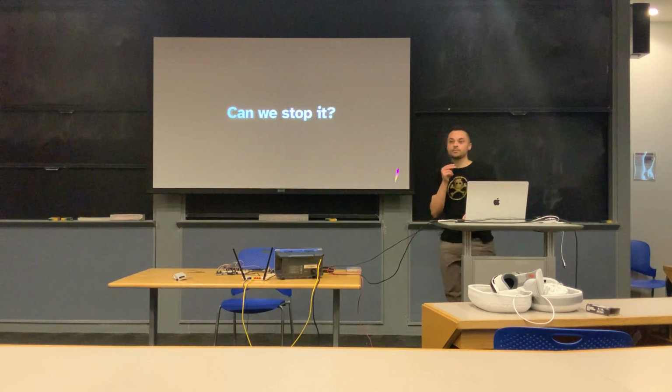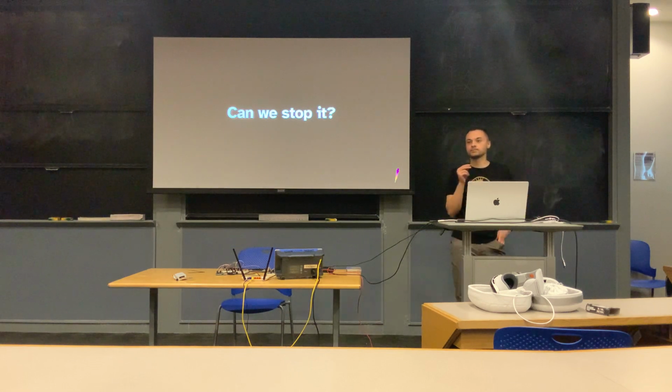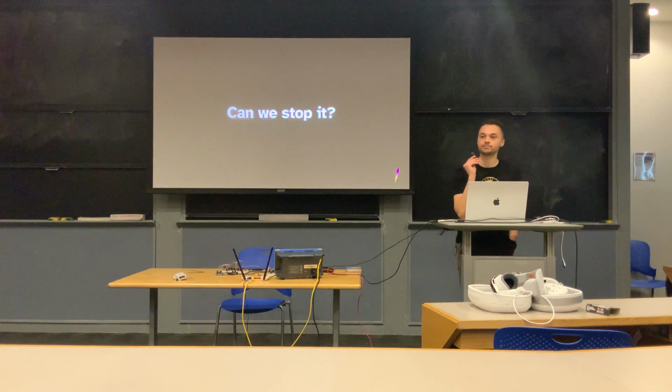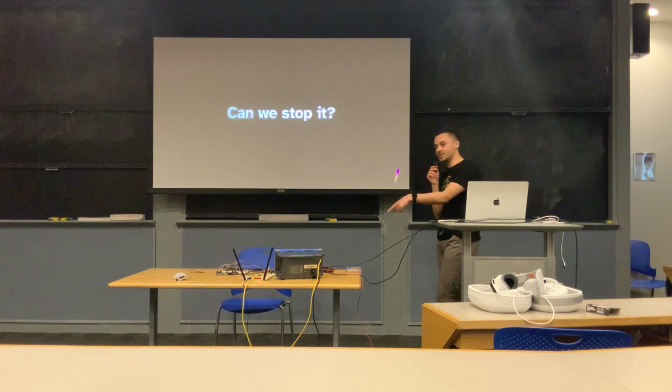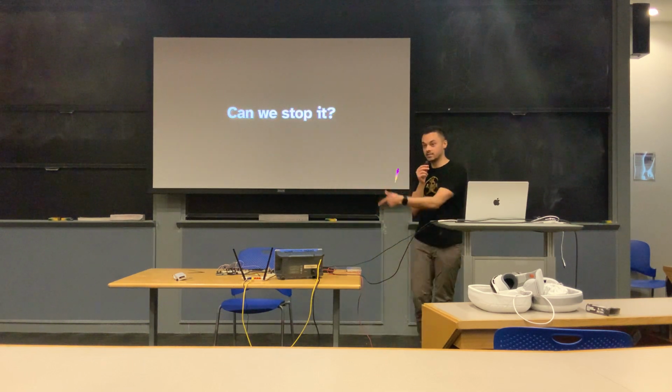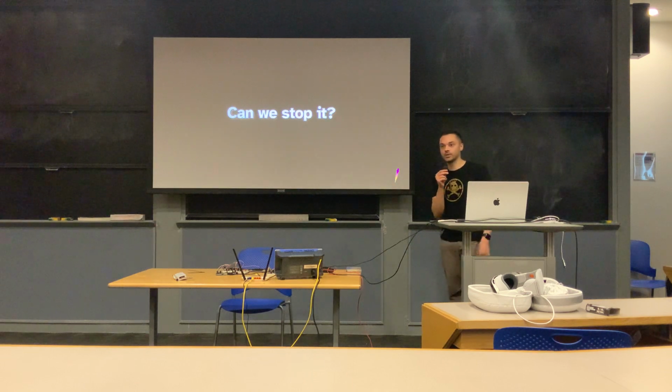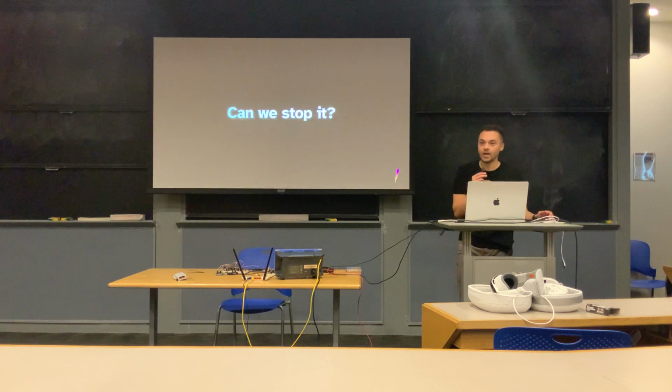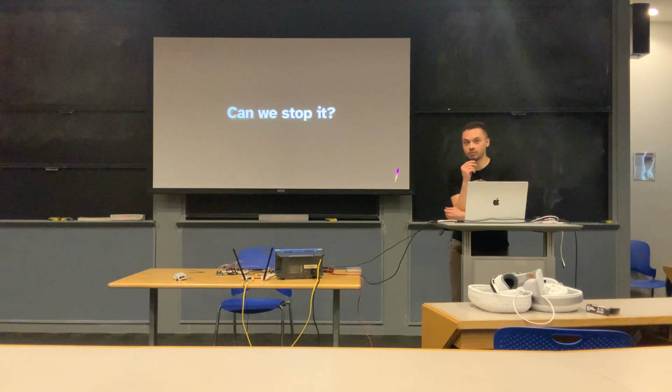So presumably you have to do a lot of iteration to figure out the parameters of your injection. Does this ever cause problems where you do permanent damage to the chip? Oh yeah. We've seen it. This is the result of many. Actually, when I did this demo, I was just hoping it wouldn't fry the memory. But I've had examples where the chip memory was just gone, so we had to reflash it. One time it was broken so badly we had to reflash the bootloader.